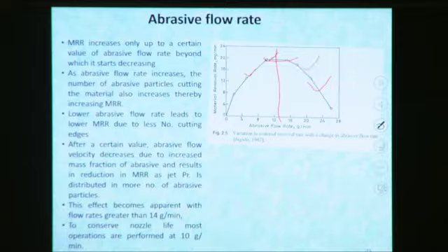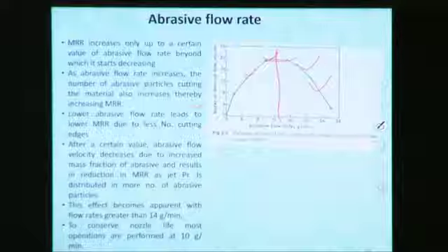As abrasive flow rate increases, the number of abrasive particles cutting the material also increases, thereby increasing the material removal rate. A lower abrasive flow rate leads to a lower material removal rate, due to fewer cutting edges. And after a certain value, as the abrasive flow rate increases, abrasive flow velocity decreases.